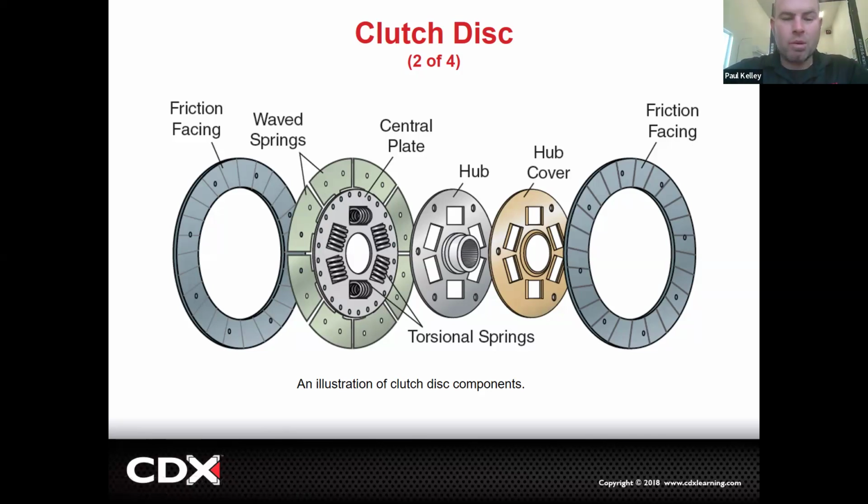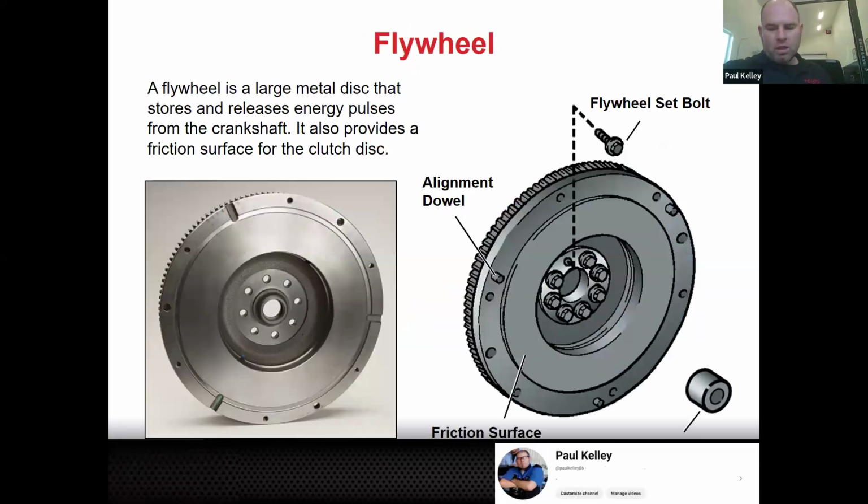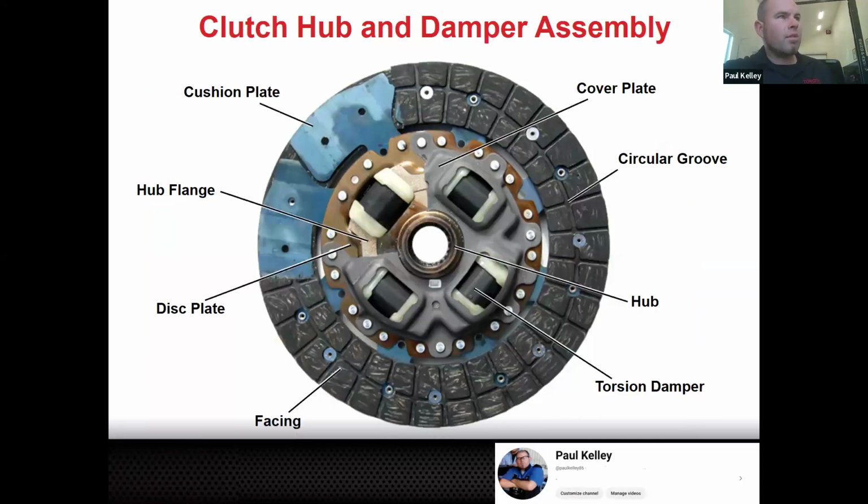Make sense? That would be very similar to a cracked flex plate. It would change with park or drive, but in a manual, that's going to really change with clutch pedal depressed, which is disengaged, clutch pedal up, which is engaged, right? That would change a lot. That could be a damaged torsional spring. Right, that's an ASE concept. We talked about the flywheel enough.